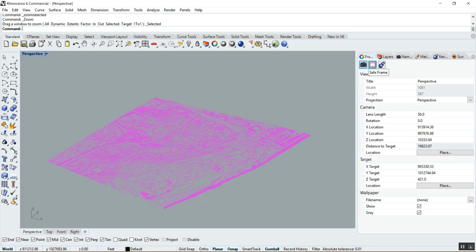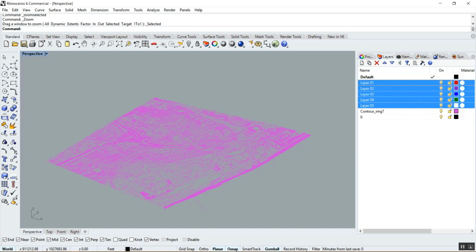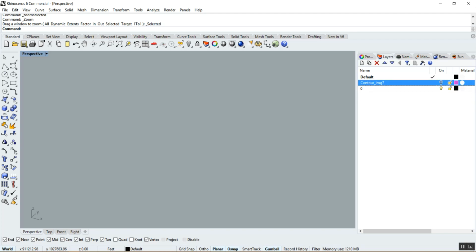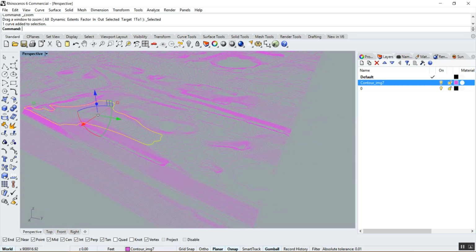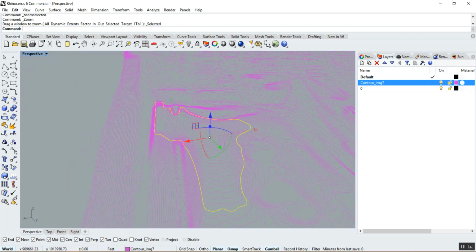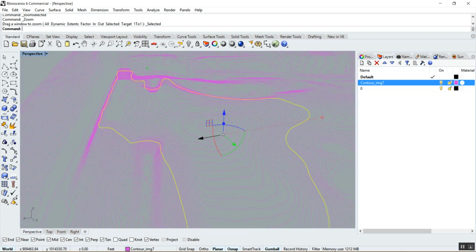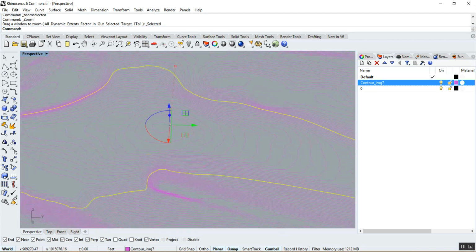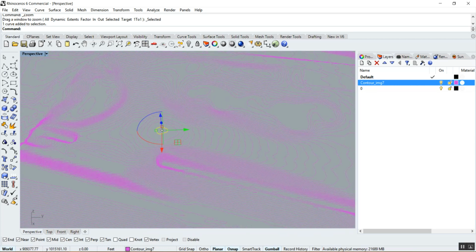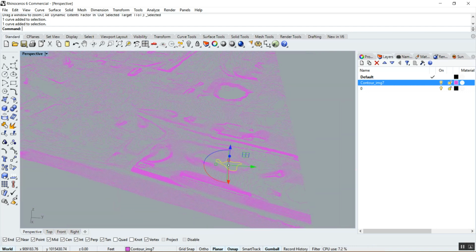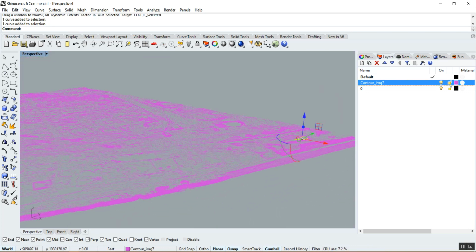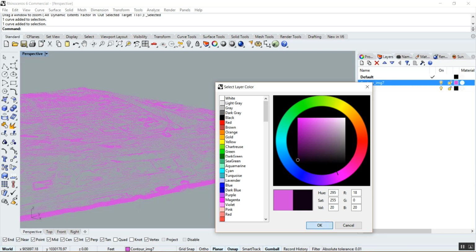Okay. So you see what happened is it basically took the contour layer here and brought it into a 3D program such as Rhino, and you see it has all the elevation data built into it. For instance, you can see the arch grounds right here. These are the contours. As you can see, contours close on themselves. They always indicate some kind of berm or depression or valley. So this is the top of that, this is the bottom of that. Let's make these black or something.